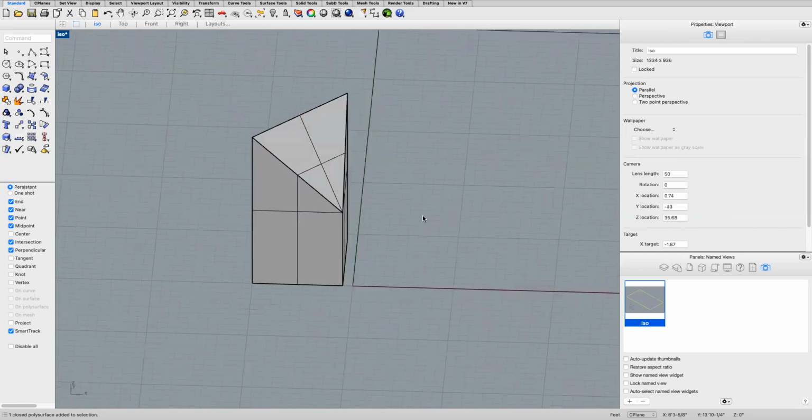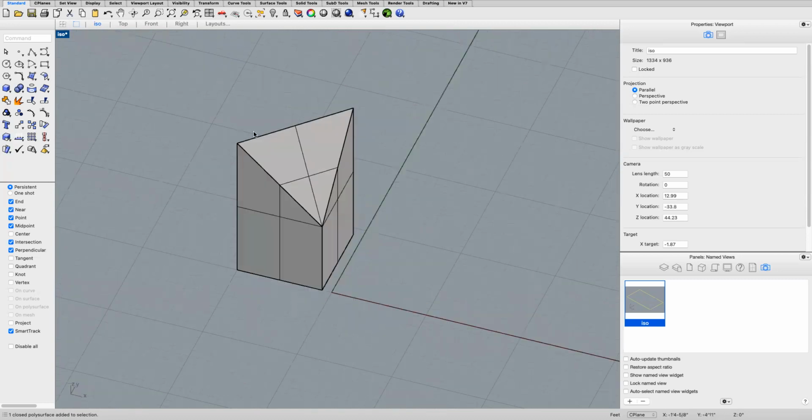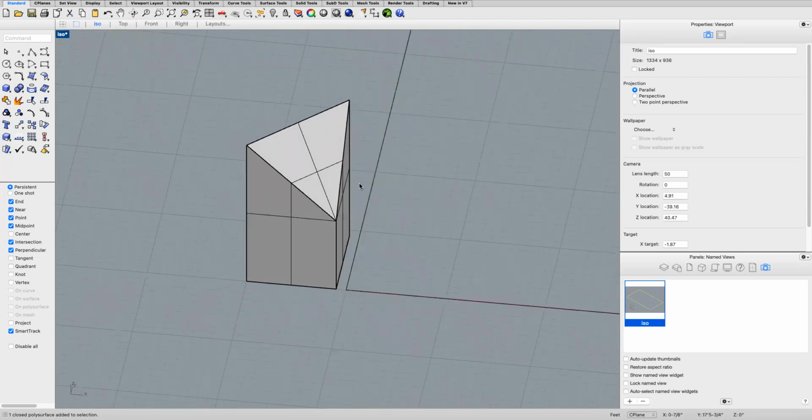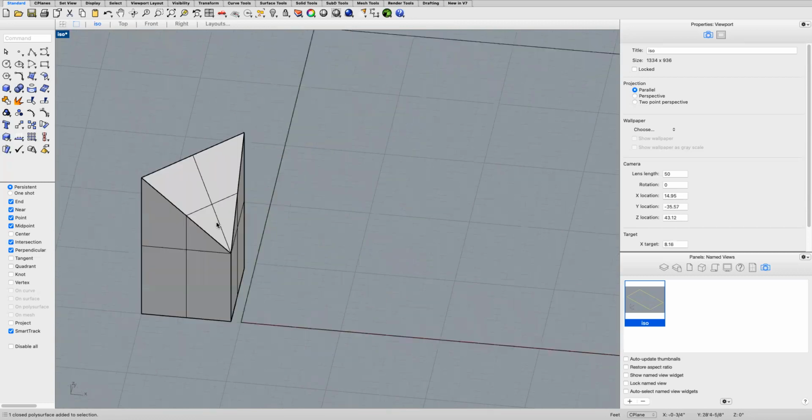And now, let's talk about the grid for a minute. You can customize your grid and you can have full control over it in Rhino. I have a 9x9 object, but my major grid lines are 10x10, and this is a unit that I want to aggregate on the site, so it might be nice to customize my grid to more accurately reflect my unit. So I will do that.